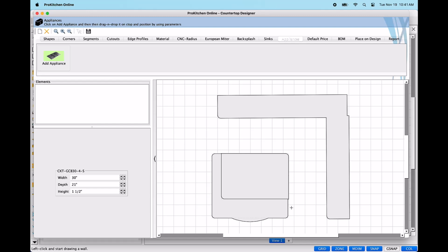The dialog box will then disappear and the mouse will now be a crosshair with the red outline of the item attached. When you hover the mouse over the countertop, the item will rotate to fit appropriately and auto-snap to specific points on the countertop. Take note of where the green dot appears on the edge of the countertop, as it will inform you of where the front of the object will be facing.